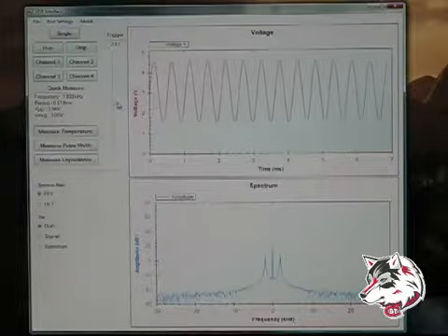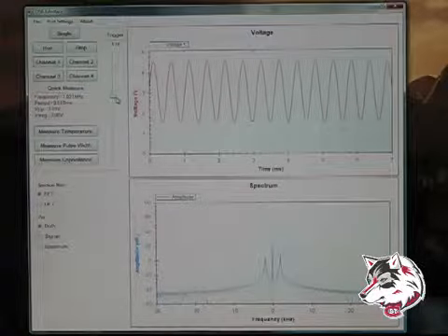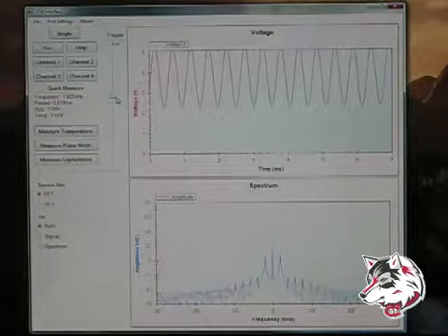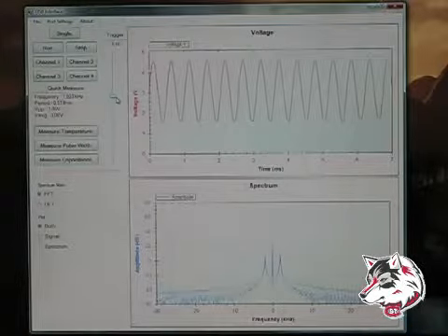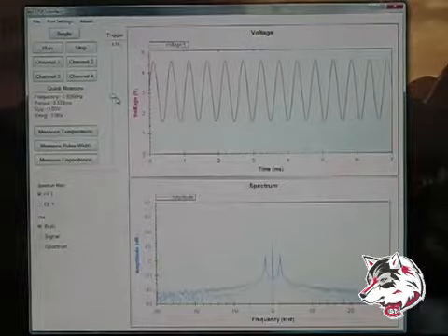Basically the only drawback to this compared to a normal oscilloscope is this has a 0 to 5 volt range, because that's the power supply on the PIC. You can go a little bit above that and it'll be alright. But any more than about a half volt above or below 0 to 5 volts, it'll reset the PIC because that's outside the range.